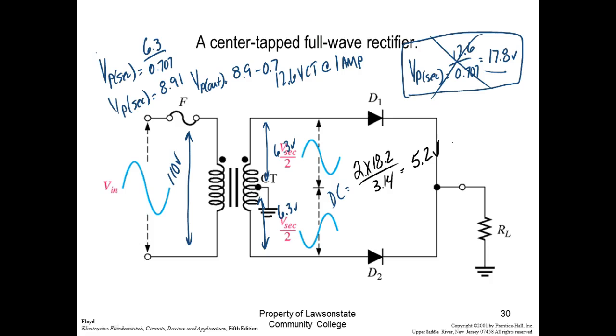I don't think I've ever taught solid state where somebody didn't put them across each other and hook both transformer leads into the same side. So what you've done is shorted out your transformer, right? There is something between this and this. If they were in parallel, there would not be another symbol between the two anodes. These guys are not in parallel.